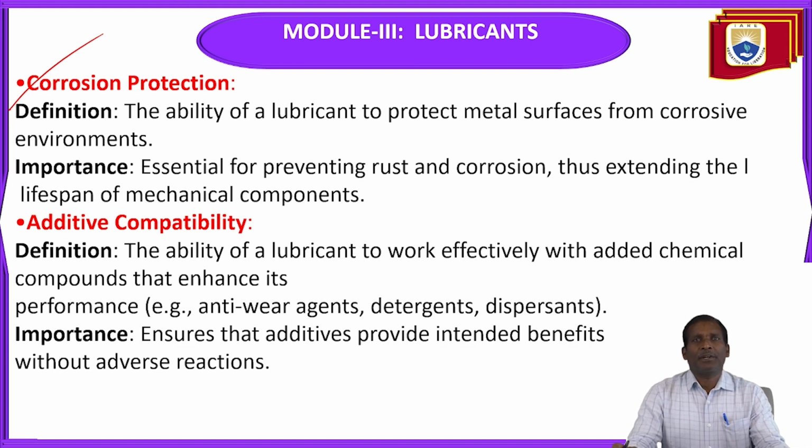So next property is additive compatibility. As per definition, the ability of a lubricant to work effectively with added chemical compounds that enhance its performance. Anti-wear agents, detergents, dispersants. The importance is that it ensures that additives provide intended benefits without adverse reactions.